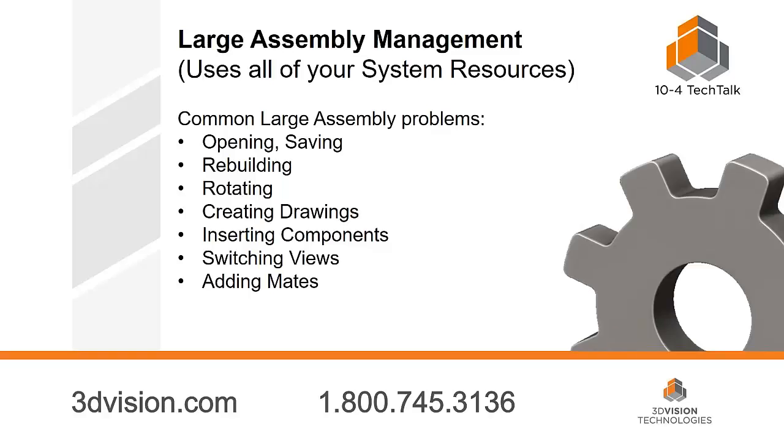A lot of people think it's a number of components that you have to hit, and then you're considered a large assembly, or maybe it's something else like that. In this case, what I'm going to say is a large assembly means that you're using all of your system resources. So common large assembly problems are opening, rebuilding, rotating, anything listed here. If you're seeing any of this stuff, you're working in a large assembly for your environment.